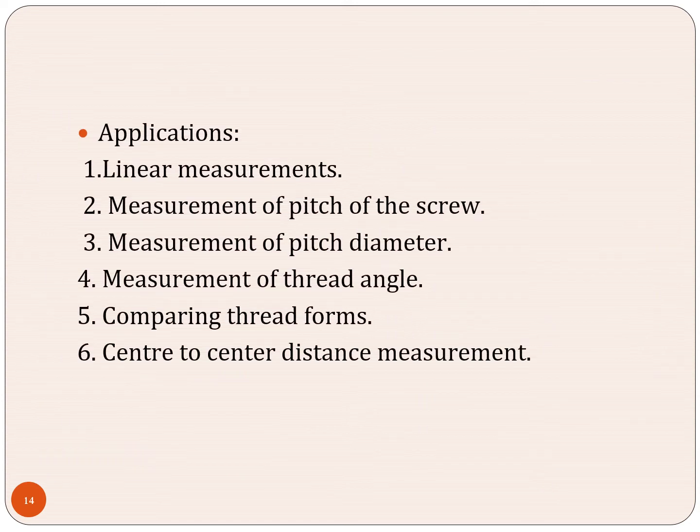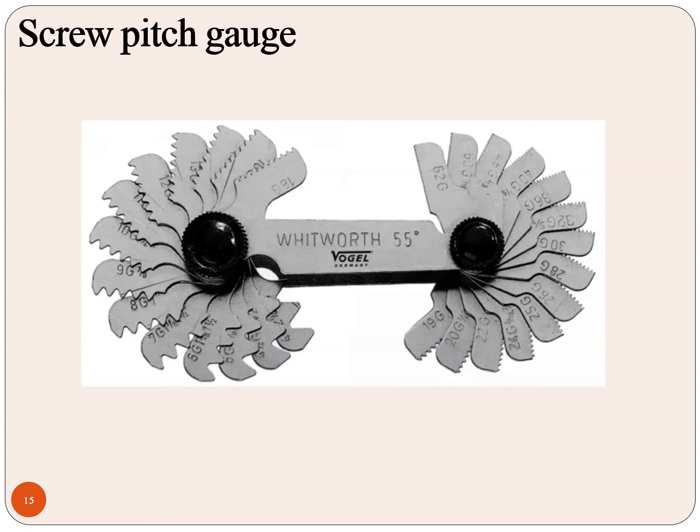The applications are to measure linear measurements, measurement of pitch of the screw, measurement of pitch diameter, measurement of thread angle, comparing thread forms, center to center distance measurement. For all these things, we can have this form of tool microscope, toolmaker's microscope. Now look at this.